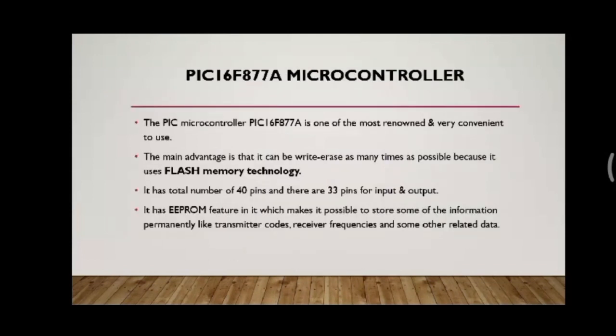The PIC microcontroller PIC16F877A is one of the most renowned and very convenient to use. The main advantage is that it can be written and erased as many times as possible because it uses flash memory technology. It has a total of 40 pins, and 33 pins are used for input and output. It has an EEPROM feature which makes it possible to store some information permanently, like a transmitter code, receiver frequency, and some other related data.